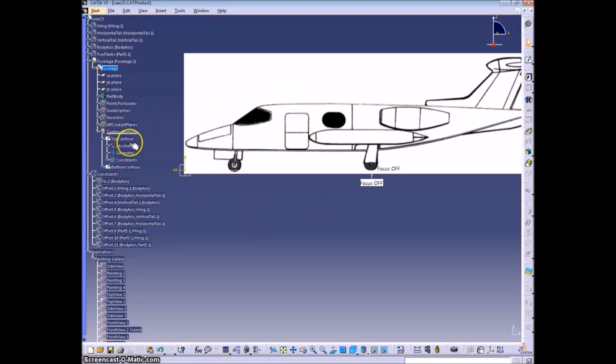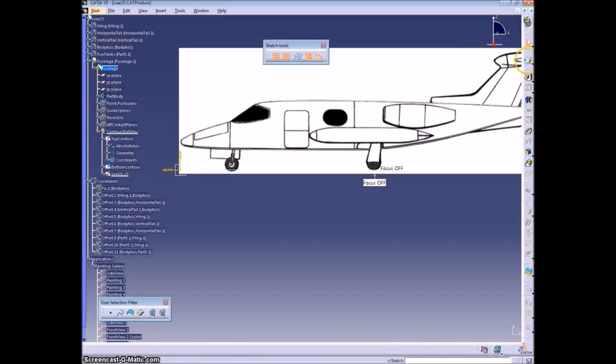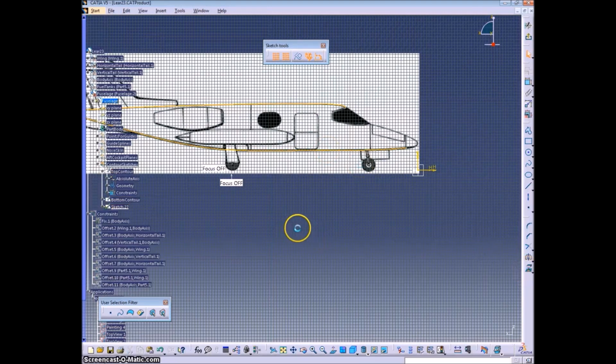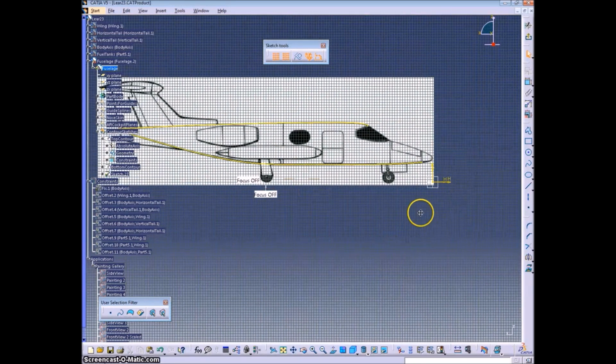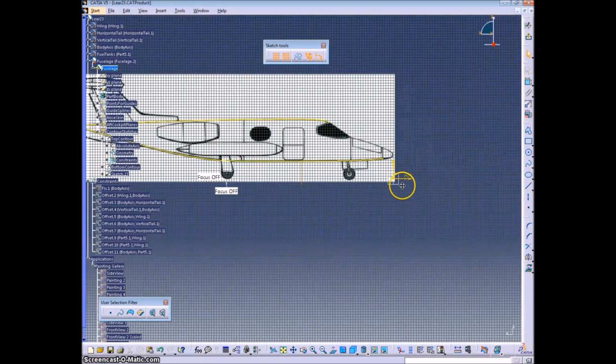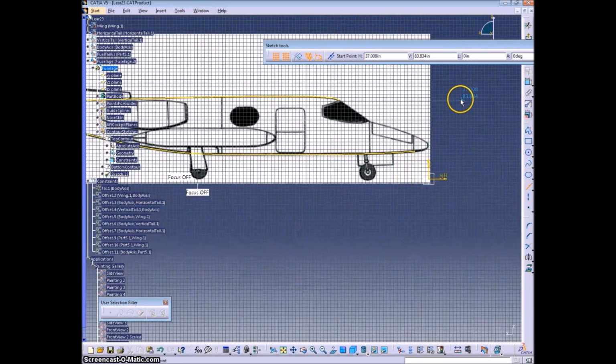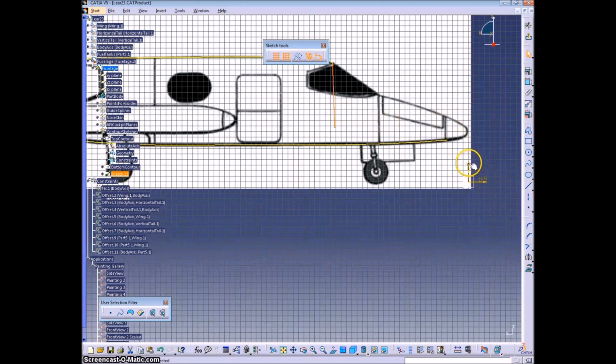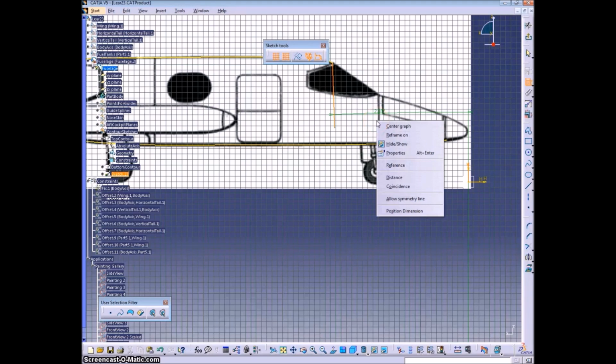Next thing we want to do is create a midline between the top and the bottom. So we'll go into a new sketch, same plane, and we'll project our previous two sketches into this sketch. And we're going to create a series of vertical lines. Generally I don't like to have it auto-constrain things because that creates problems for you. So if you hold the Shift key when you're selecting points for the line, that turns off the auto-constraints. But then we'll just constrain this vertical to, or parallel to, the V direction.